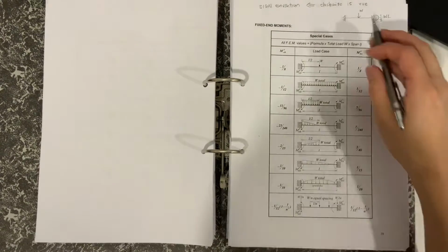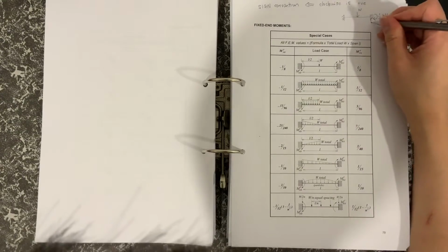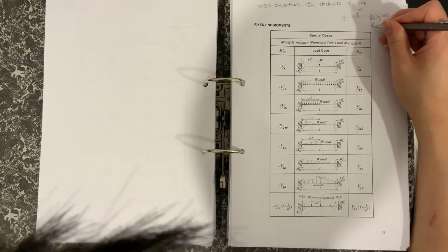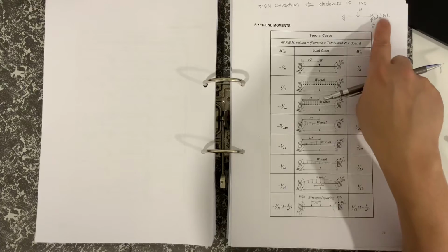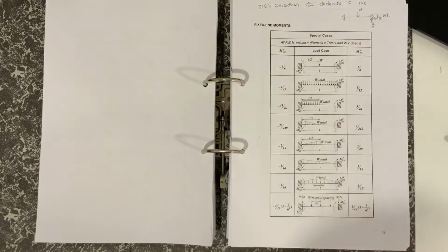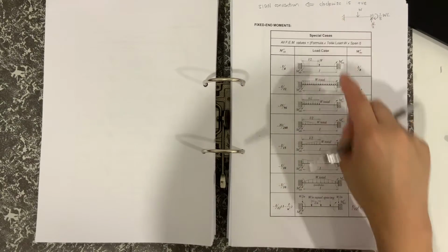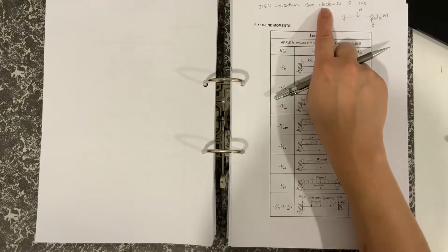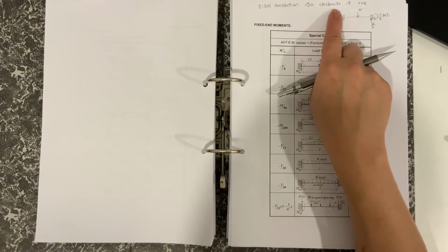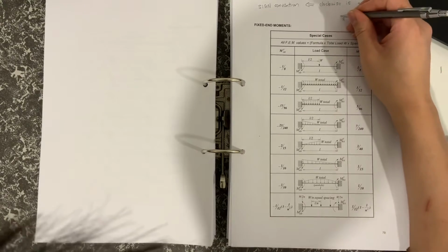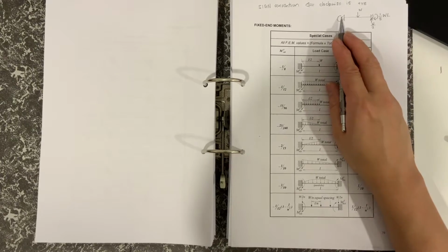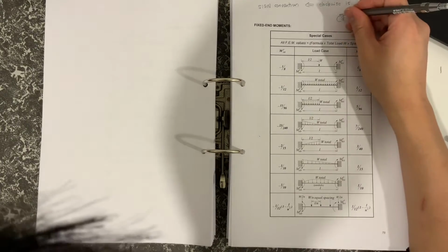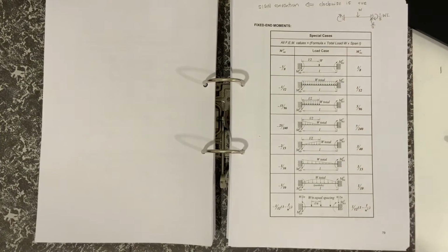Okay. So we've got load of W, so reaction there of course W/2, and then the fixed end moment on the right hand side is 1 over 8 W times L. Okay, so that's how to interpret that table. Now we look at the other side, and remember we've now got a convention which is clockwise is positive. So I'm going to draw the reaction here in a clockwise direction. So if that's clockwise, clockwise would be also acting in that direction there.